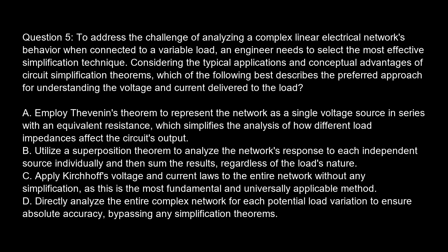Option A. Employ Thevenin's theorem to represent the network as a single voltage source in series with an equivalent resistance, which simplifies the analysis of how different load impedances affect the circuit's output. Option B. Utilize the superposition theorem to analyze the network's response to each independent source individually, and then sum the results, regardless of the load's nature. Option C. Apply Kirchhoff's voltage and current laws to the entire network without any simplification, as this is the most fundamental and universally applicable method. Option D. Directly analyze the entire complex network for each potential load variation to ensure absolute accuracy, bypassing any simplification theorems.